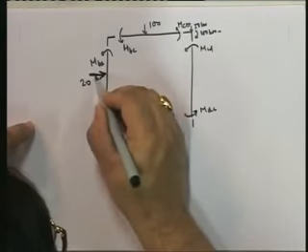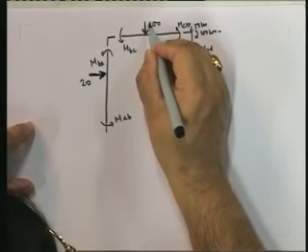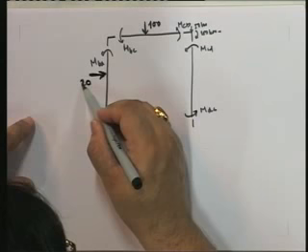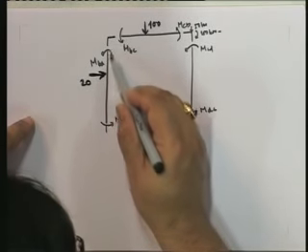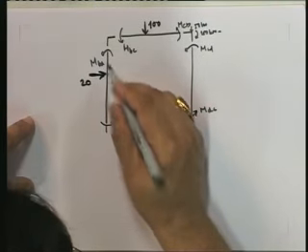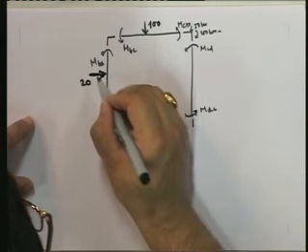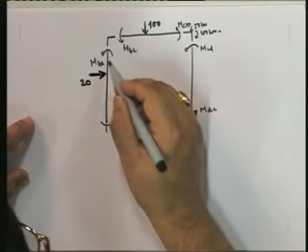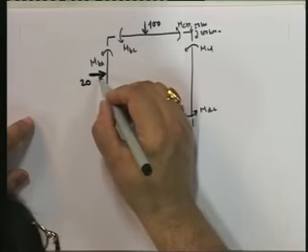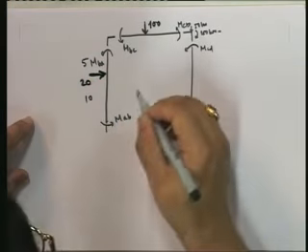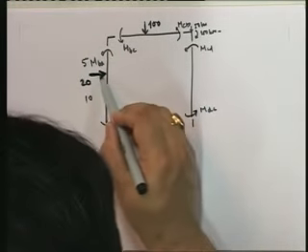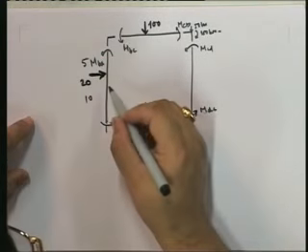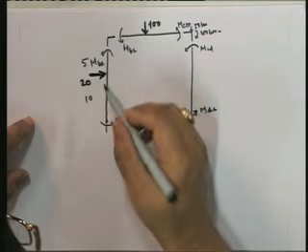Now one aspect that is very important is that when you have loads acting on the member, you need to find out the reactions at this. Think of this as a simply supported beam with MAB and MBA. What I need to compute, for getting the virtual work properly, is the reactions at the end of the member due to this. Since I'm considering it to be a simply supported beam, the reactions are going to be equal to what? This is 5, this is 10. I'm only finding out the reaction due to the load only. Remember that. Only the load, not due to the unbalanced moments, etc.